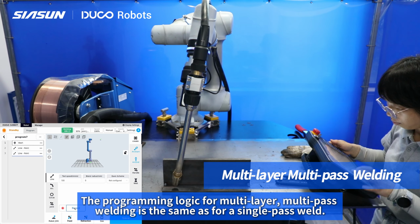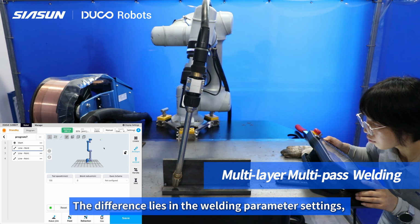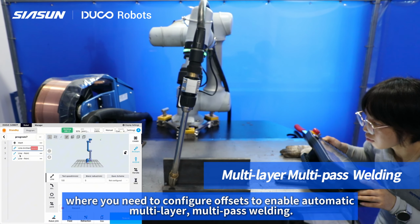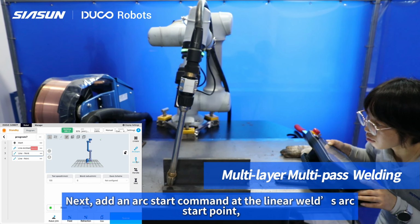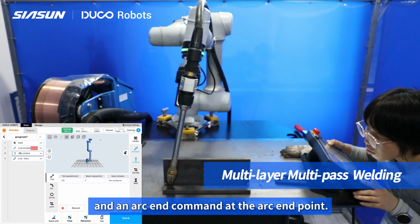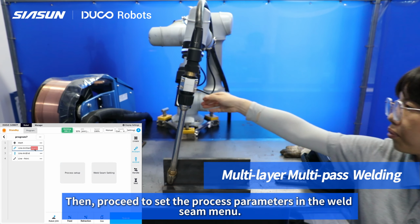The programming logic for multi-layer, multi-pass welding is the same as for a single-pass weld. The difference lies in the welding parameter settings, where you need to configure offsets to enable automatic multi-layer, multi-pass welding. Next, add an arc start command at the linear weld's arc start point, and an arc end command at the arc end point. Then, proceed to set the process parameters in the weld seam menu.